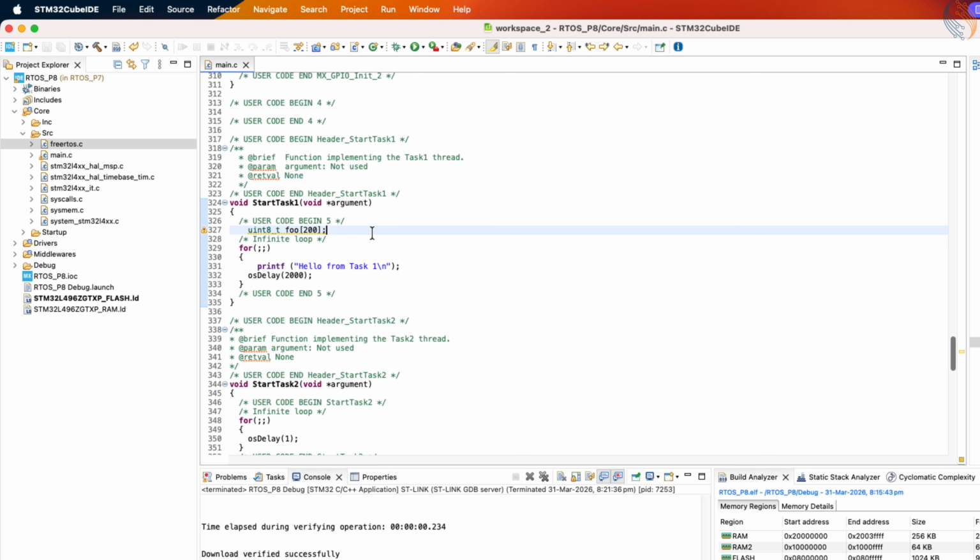This situation perfectly highlights the real danger of stack overflow. It doesn't always cause an immediate system fault or crash. Instead, it can silently cause data corruption in adjacent memory areas and create unpredictable behavior throughout your system until the corrupted memory is actually accessed or used by the processor. This is why early detection is so critical.